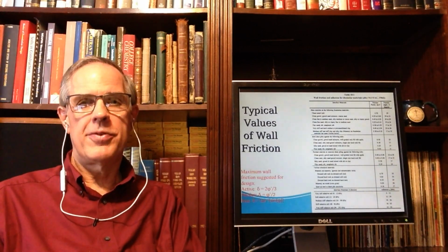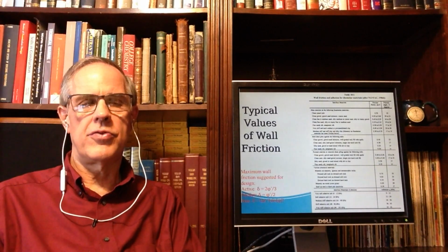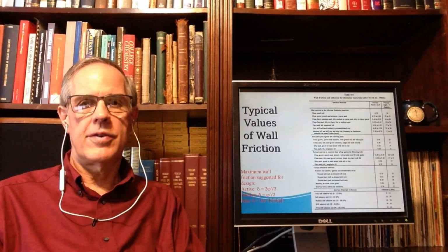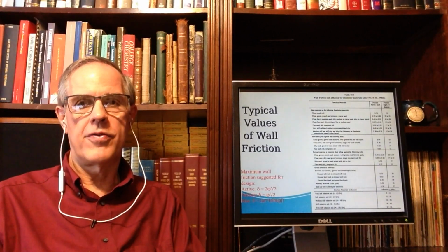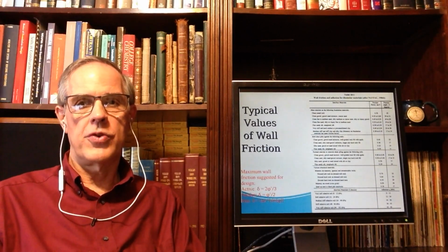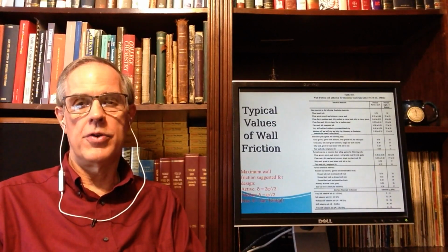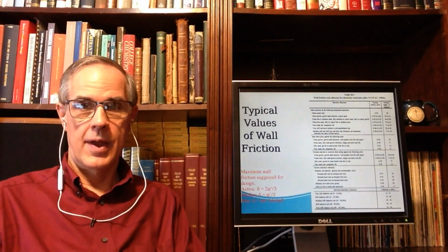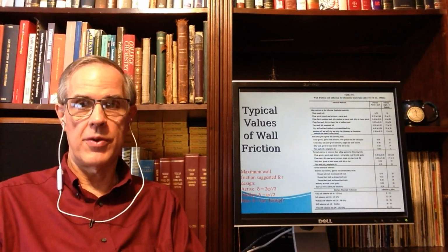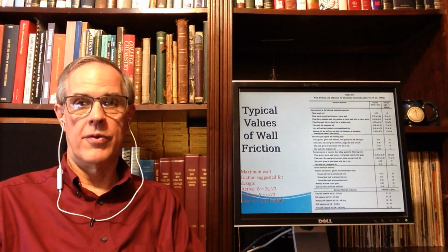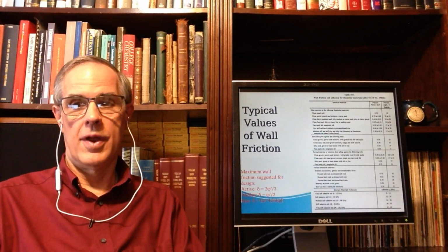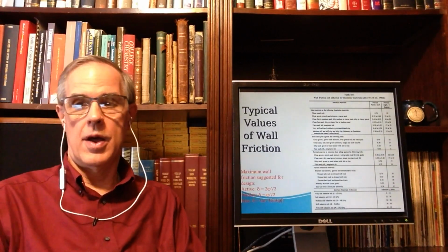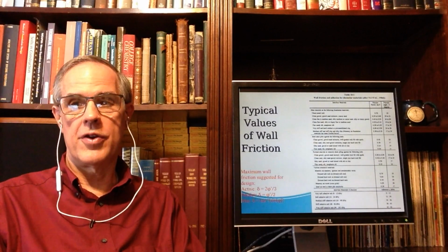There are certain types of walls where I would use Rankine theory under any circumstances. Just as a recommendation, without wall friction, those would include pultruded vinyl or aluminum sheeting. I will almost use Rankine exclusively with those. Also, MSE walls tend to prefer Rankine earth pressure coefficients. I've got some maximum wall friction suggested for design down there in the corner.